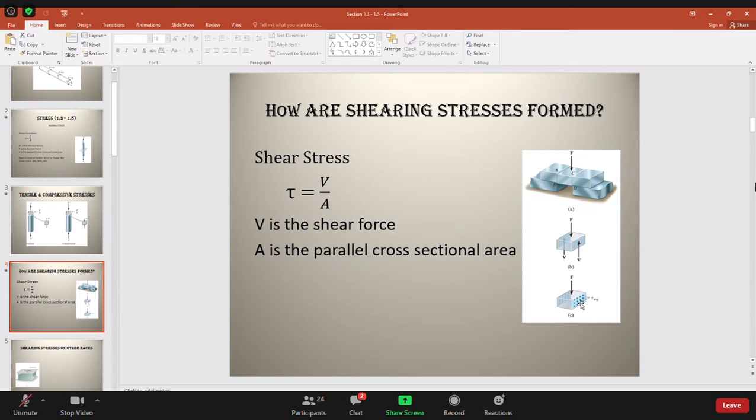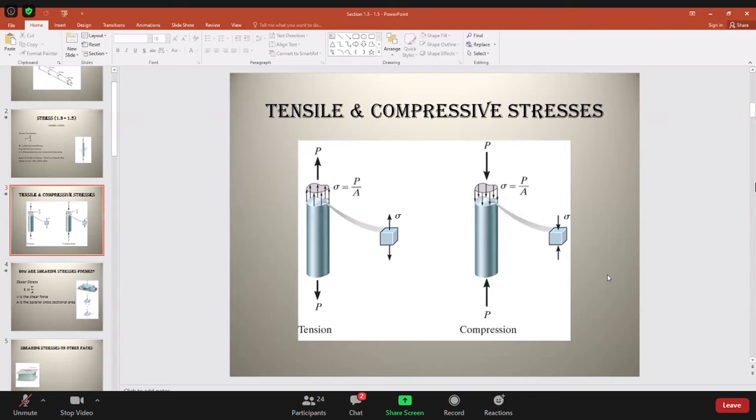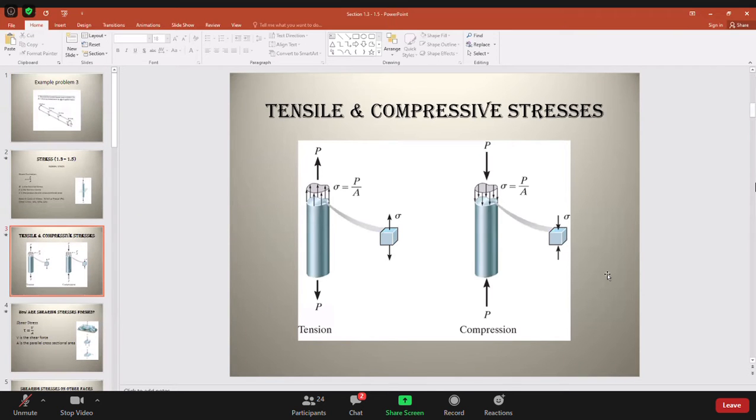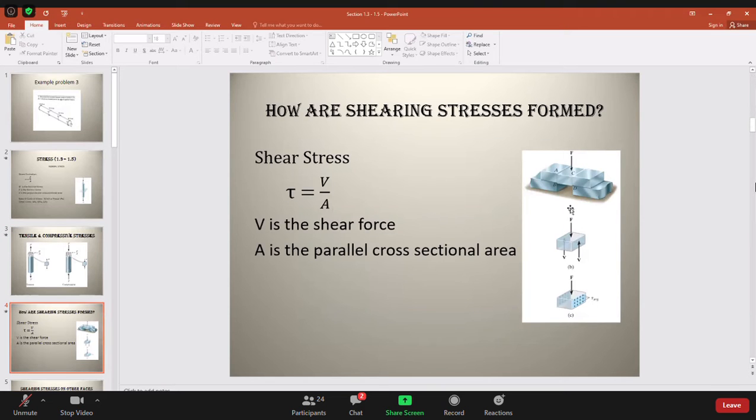The way to show shear stress is by small little arrows all over the area, like this. Just like we were showing the normal stress by perpendicular arrows all over the area, remember that? I can go back a slide and remind you again. Here we are showing the normal stresses as arrows perpendicular to the surface area. And for shear stresses, we show small little arrows lying along the surface, going all over.